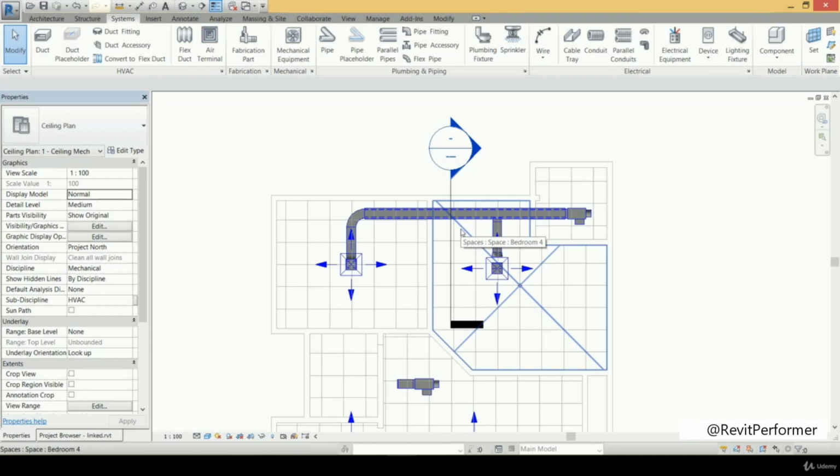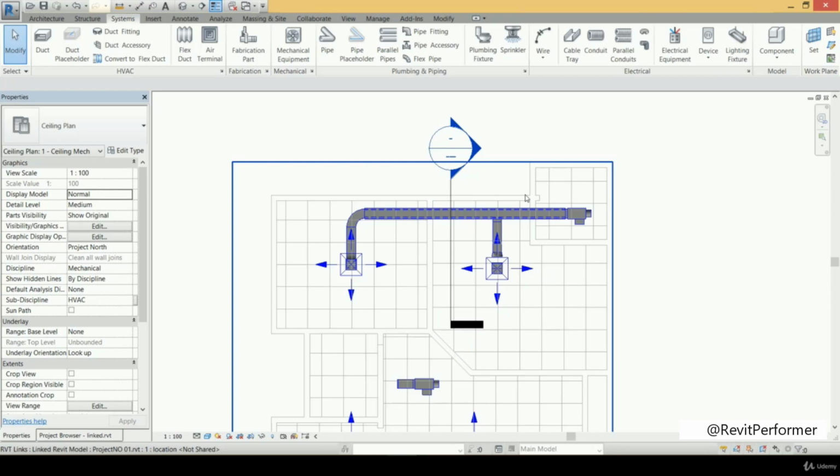And now after making the design, we need to check that our design is being done well or there is no faults inside our design. As in some cases, there may be some faults inside some ducts or some disconnected ducts, or for example, there may be some misconnections or some ducts that you didn't put the cap at the end of it. So we need to check all of that to check that there is no problem at our design.